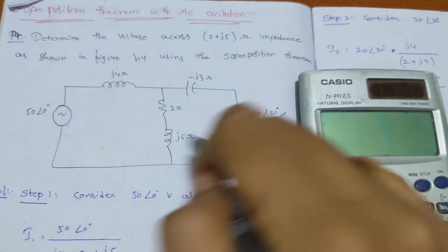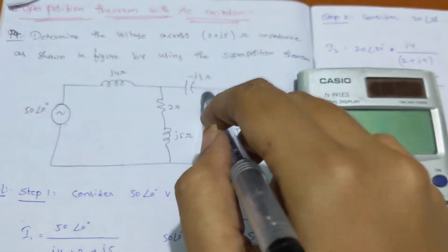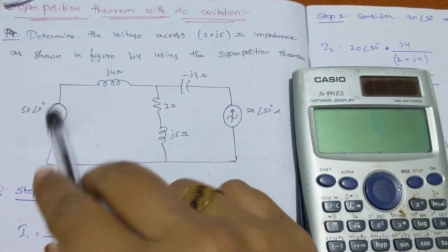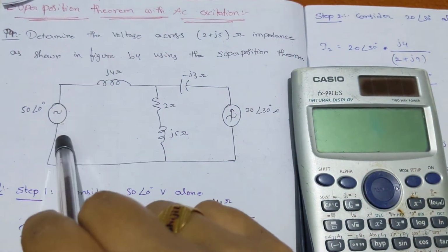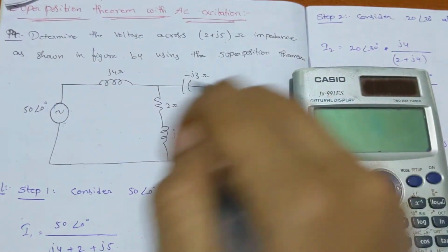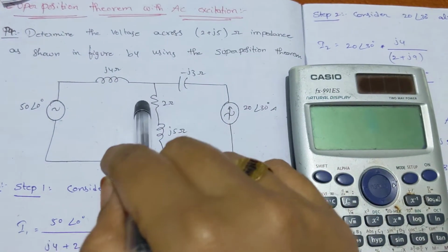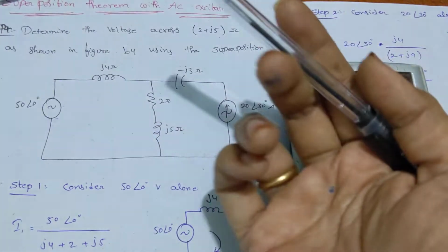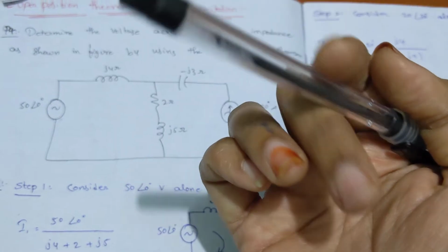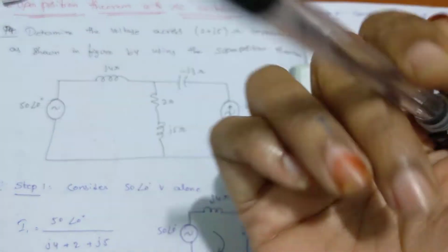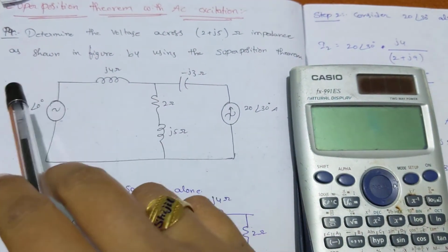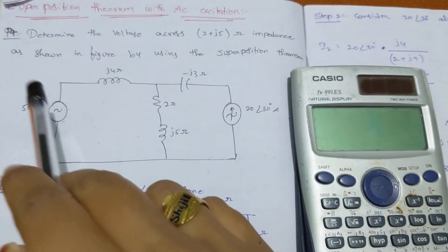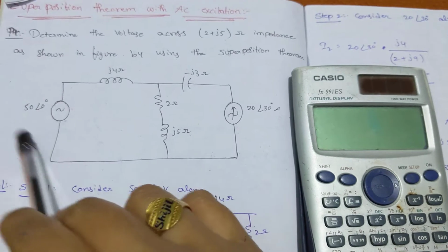If the circuit consists of more than one source, you consider one source at a time. The summation of either voltage or current, which you may call the response, is the algebraic sum of the responses you get when you consider one source at a time.